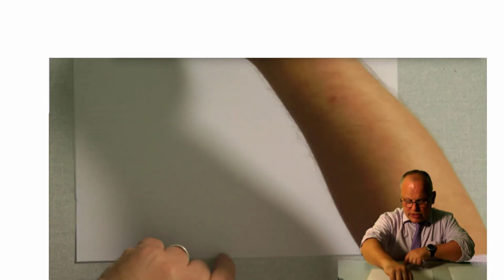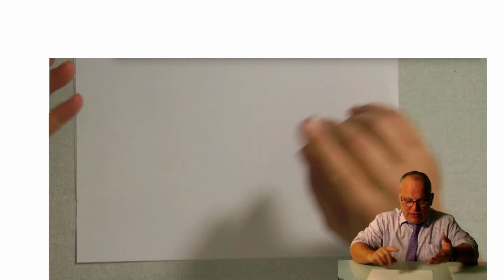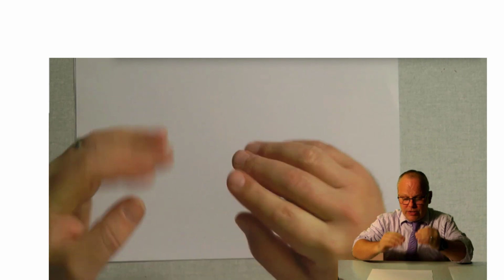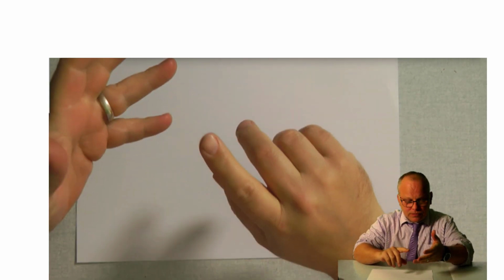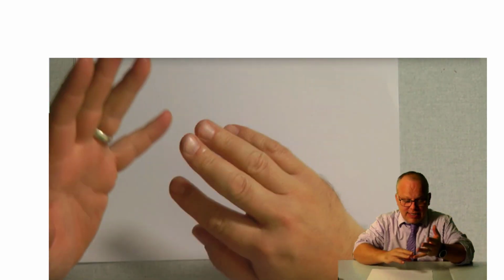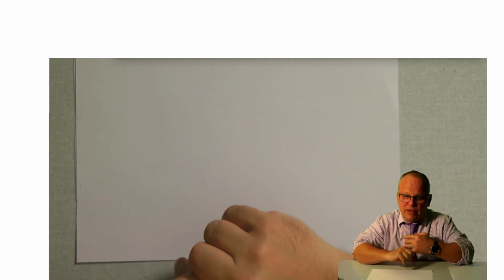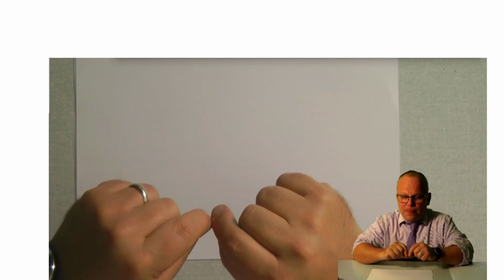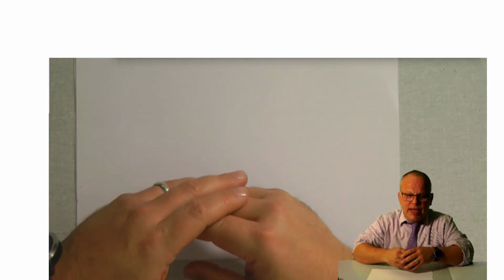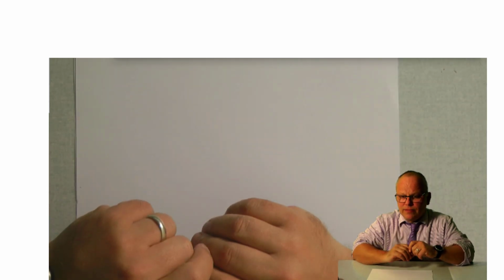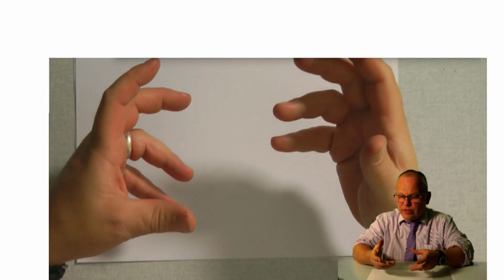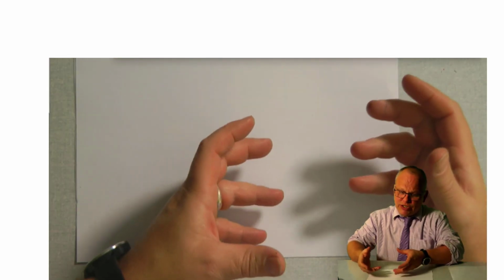When I'm drawing today, I'm going to work with either 9mm, 12mm or 18mm plywood. Those are standard thicknesses. If I work at 9mm, or I could potentially go 6mm, if I worked at 6mm or 9mm, it gets quite thin, and so it's hard to cut a joint into it or to put a screw into it. If I go with the 18mm, it gets really heavy. So although I can cut a joint into it, it becomes really challenging to use.